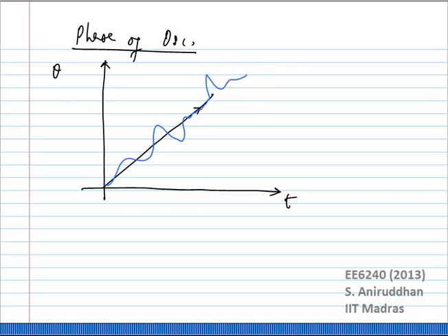Because there is nothing else inherent inside the oscillator which operates on the phase, we have to be very careful about any noise injected into the oscillator which changes its phase. Obviously, the phase of the oscillator is an important characteristic because the phase directly decides the frequency of the oscillator and the frequency response. If you look at the output, you don't want to see these frequency sidebands.